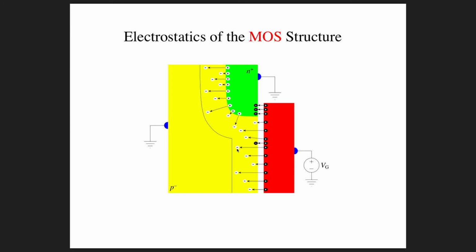But the idea here is that the initial gate charges that we have to put in go into creating this channel region. And once we get up to threshold, then basically every additional gate charge winds up dragging in a mobile charge, and the depletion region doesn't get any thicker. The depletion region underneath the gate doesn't get any thicker beyond that point.